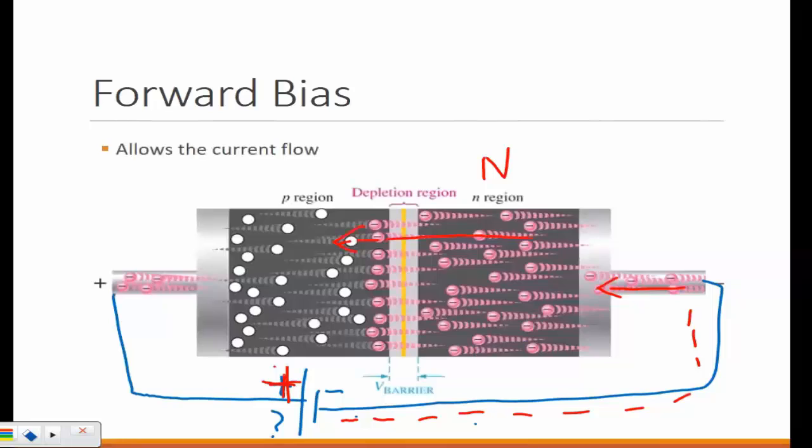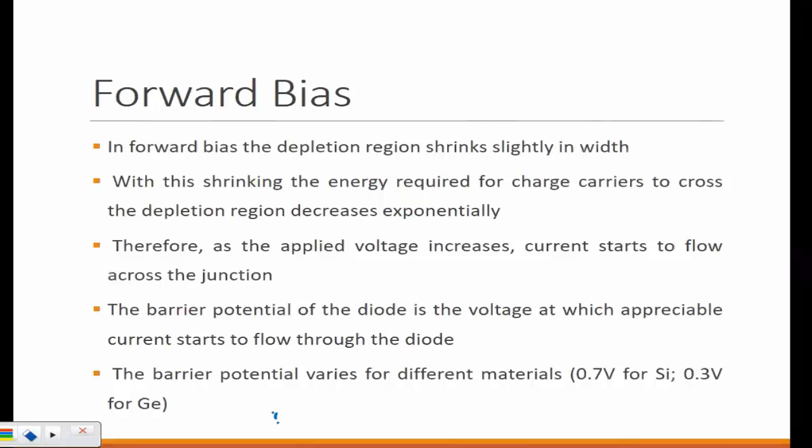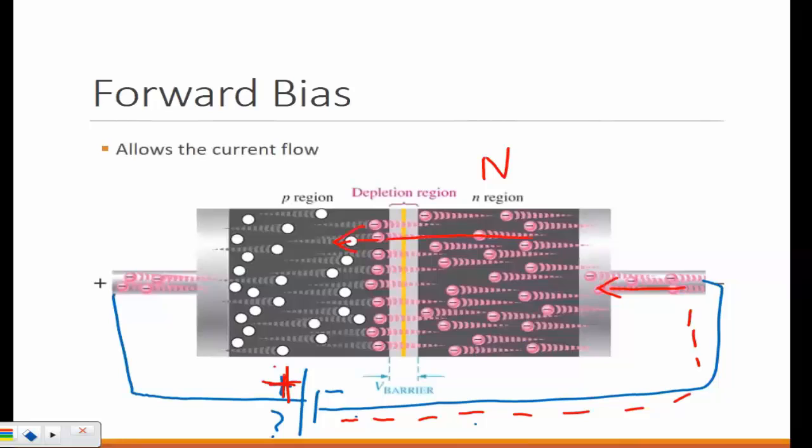Previously you asked whether the junction width is ever going to get lower, right? Remember that 0.7 volts, we always say theoretically 0.7 volts. But when you're making the junction forward biased, you observe that we already have electron current being shown here, right? But what we are also missing is, when the electrons are going this way, what about the holes?